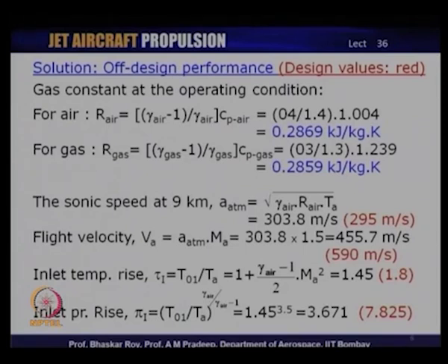Correspondingly, the inlet temperature and pressure rise, which is the conversion of kinetic energy to pressure, that is ram pressurization, as we have called it in this lecture series. Now, this inlet temperature rise comes out to be 1.45 using the normal isentropic relation of conversion of kinetic head to static head. The corresponding design value was 1.8.